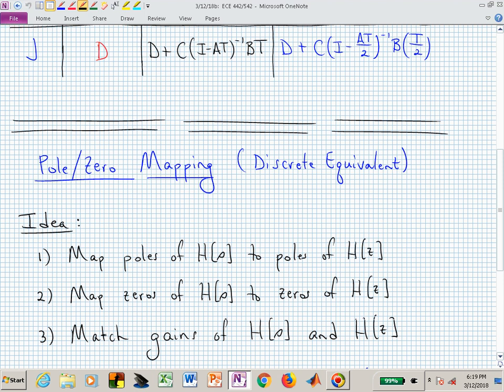Here, with the pole zero mapping or the numerical integration, we could take a string of numbers and boom, pop out an answer. We don't need a continuous waveform in this process. So these are for like controllers or filters. That's why we might want scenario number 1. We don't need to worry about the hold device.